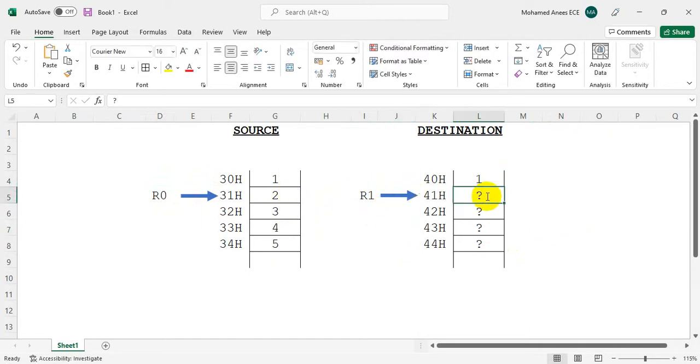Afterwards, I shall copy the next byte to the destination. For this process, I shall continue until all the bytes have been finished. So for that, I will have a loop count. In my program, the count of the loop, or the count of the block, is equal to 5. So I will initialize some register with this block size, and then I will repeat this process. This is the logic of this program. Now we shall proceed to see how to write the code.